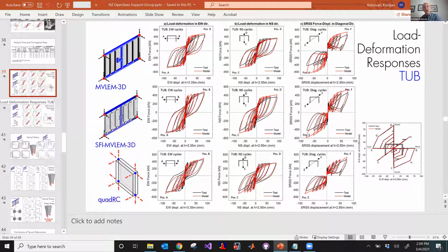These elements have a linear elastic out-of-plane behavior, so unfortunately you cannot capture any punching. You would have to find some element that has nonlinear through-thickness behavior to get the punching. So these elements are not for that. Is there any such element that can help me model a slab, such as composite? Maybe there's some kind of a. Is it a 2D problem or a 3D problem? 3D and cyclic.